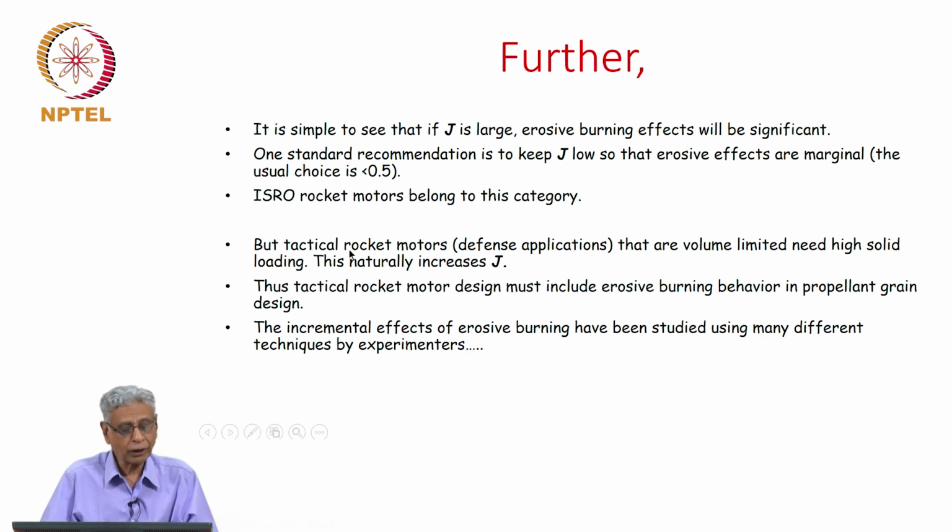But tactical rocket motors meant for defense applications are largely volume limited, and they need high solid loading. This naturally increases J, tending towards 1. Thus, the tactical rocket motor design must include erosive burning behavior in the propellant grain design. The incremental effects of erosive burning have been studied by many different techniques by experimenters.